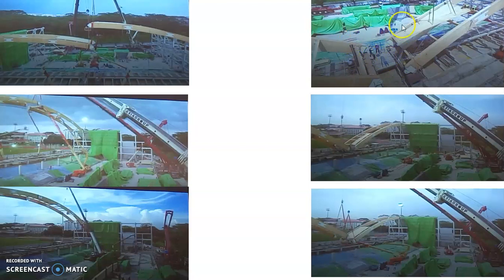So they actually fabricate the components on site. Then after that, they use 2 cranes to lift both ends of the roof. Okay, to lift it up. Once they lift it up, they join at the center, and you complete one bay, and they then move over to carry out the next bay. There are around 6 to 8 bays that make up the total roof.